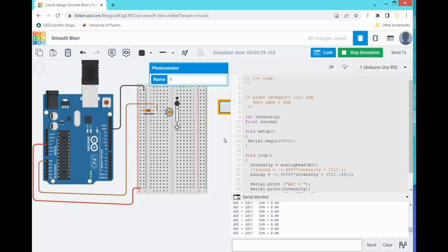The idea was how we take a sensor, in this particular one a photoresistor, whose resistance value changes according to light intensity, and use it in a voltage divider setup, have that number read by the Arduino, and after that convert it to something that makes more sense. You cannot leave things on the ADC side because they don't make any sense.